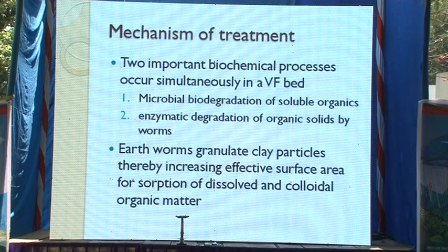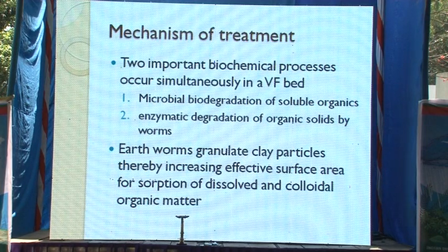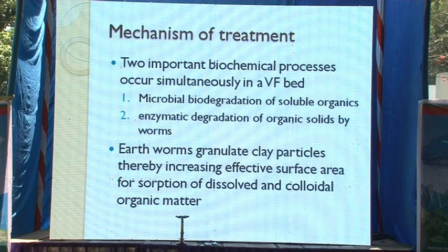And there are enzymes generated by earthworms, which degrade the small colloidal solids. So there is no pre-treatment required. You can simply take the whole wastewater into it. Earthworms also granulate clay particles. You must have seen their excreta, which is granular in nature, and that increases the surface area, giving more sites for reaction, and the rate of removal also increases.